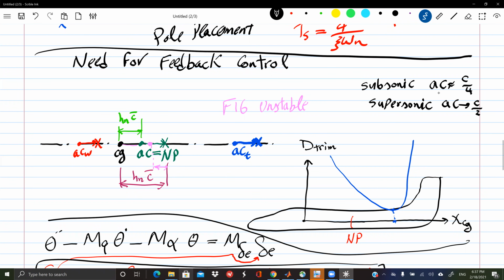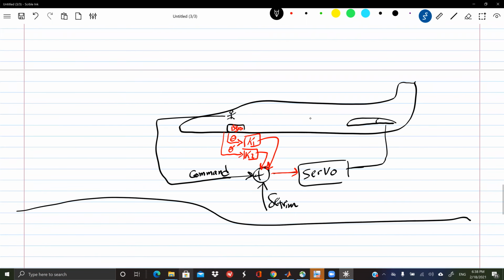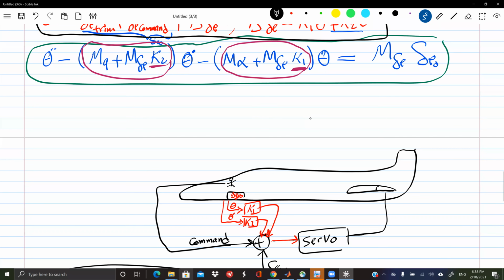No, it's aerodynamics. It's coming from the air, and this is just the physics of the air. Turns out if you're flying subsonic, the physics of the air gives you your neutral point at quarter chord, but the physics of the air changes from subsonic to supersonic. And you have no control over this because this is really the physics of how much the air is responding to your motion. It's like CL is 2 pi alpha. This is really the physics of the air. You have no control over it. Yeah, okay. I had no idea how you would physically do that, so I was very confused. Thank you. You're welcome.